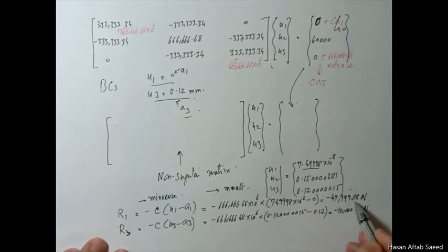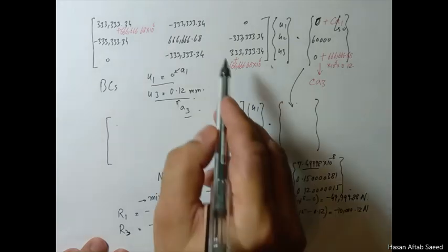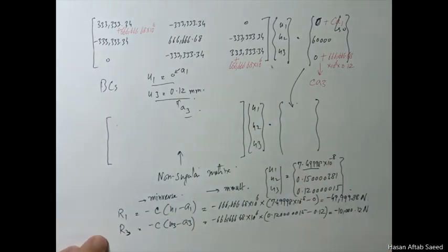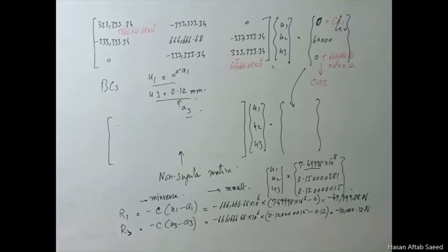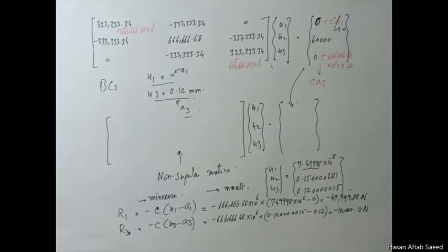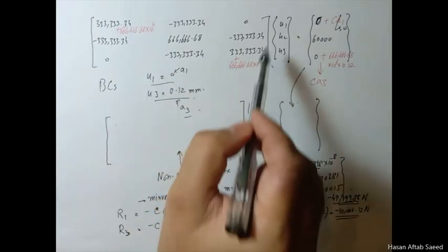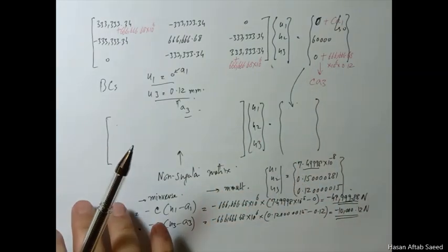But this one has very slight error here, and that error is because you never end up applying the same value of the boundary conditions. Part of the error is this. The other part could be computational error, but this one has an extra component of error. And once you have these, you have verified your penalty method gives you the correct answers, and it is much simpler. This reaction forces calculation as well as the application of boundary conditions, much simpler than any of the partition methods you have studied before.